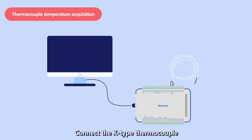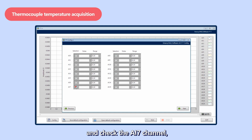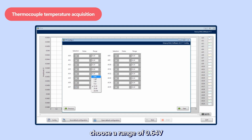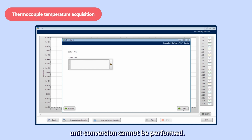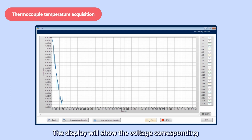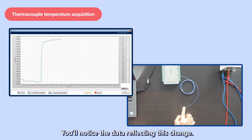Connect the K-type thermocouple directly to the analog input channel of the acquisition card. Open the software, set the relevant parameters, and check the AI7 channel. Because the signal output by the thermocouple is relatively small, choose a range of 0.64 volt and set the sampling rate to 5. Because the general acquisition card does not have cold junction compensation, unit conversion cannot be performed. After the settings are completed, start the data collection software. The display will show the voltage corresponding to the current ambient temperature. If you increase the ambient temperature, you will notice the data reflecting this change.